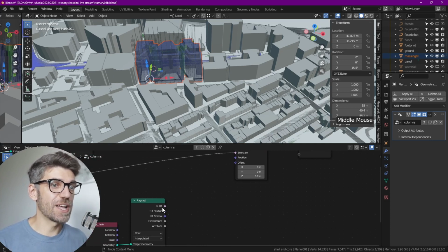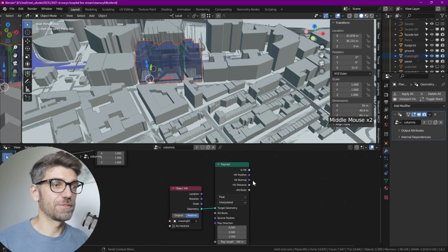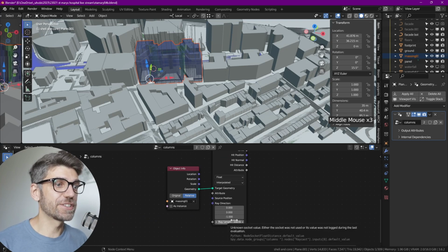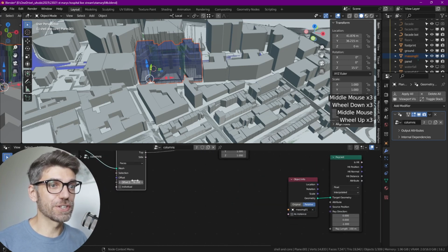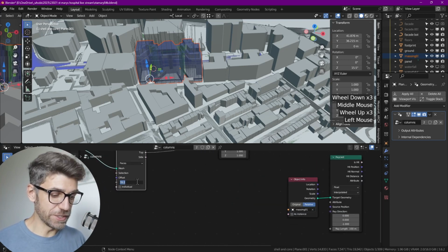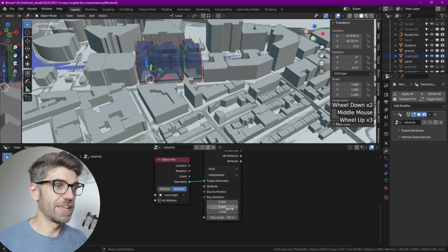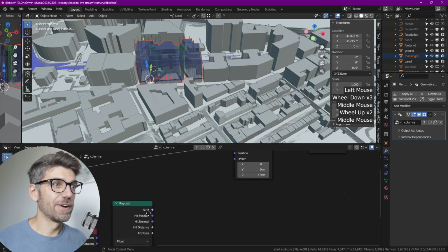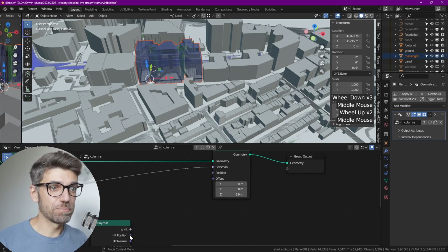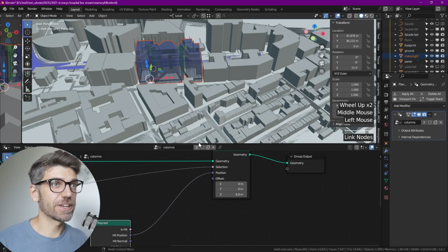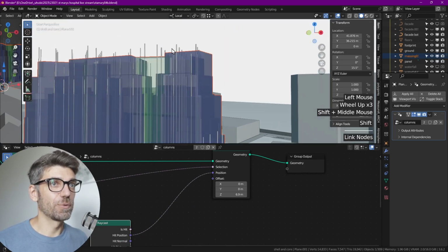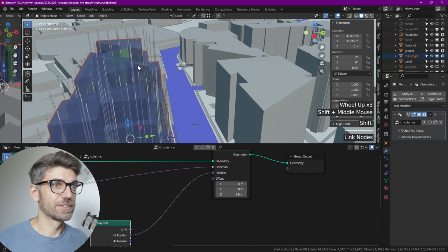Fantastic. Now we're going to use this hit position, and we want to make it go down. First off, the extrusion distance here should be something quite small. Let's try 20 meters. Next, the ray direction of the raycast should be positive. And now, hopefully this works. Hit position. Let's check. Did that work or did it not work?